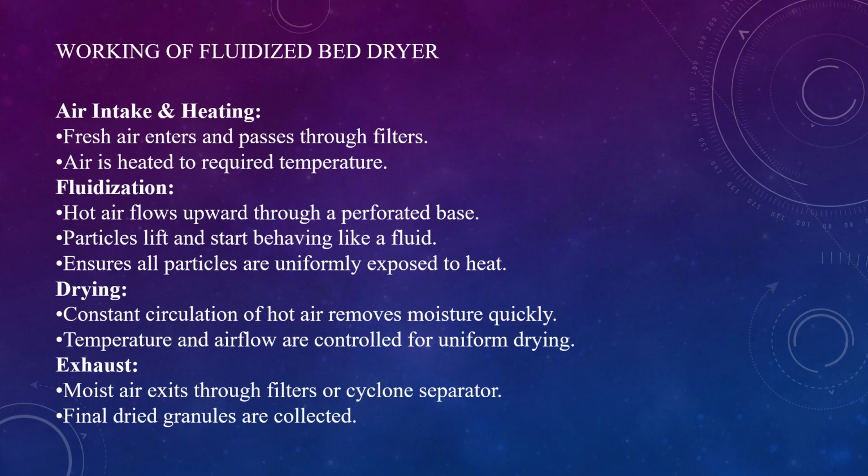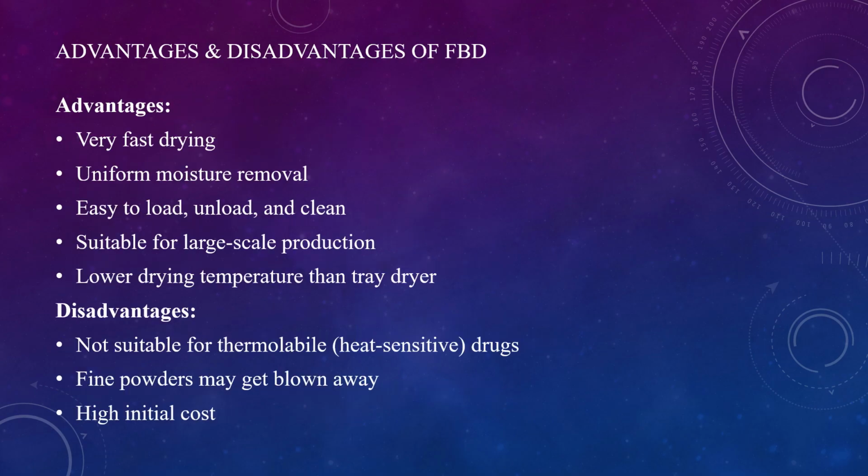Next, let us look at the advantages and disadvantages of using FBD. The fluidized bed dryer has many advantages. It dries materials very quickly, provides uniform moisture removal, and is easy to load, unload, and clean. However, it is not suitable for sensitive drugs. Fine powders may get blown away, and the equipment cost is high.